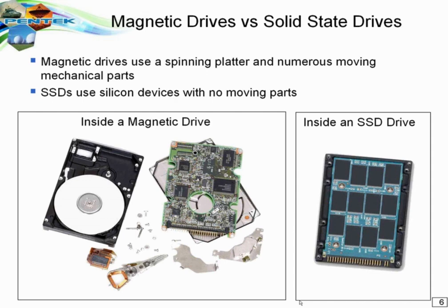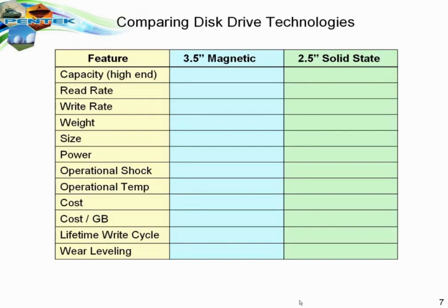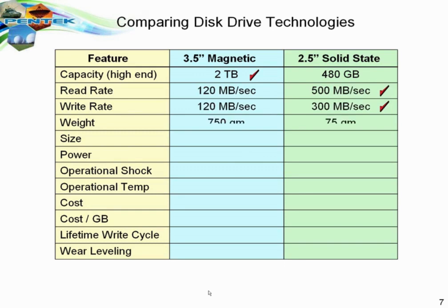For the analog I.O. module, we use PCI Express links, first between the I.O. module and system memory, and then between the system memory and the RAID controller. So all of the data flows directly across these hardware-controlled DMA links that use PCI Express to achieve the speed that we need for the operation.